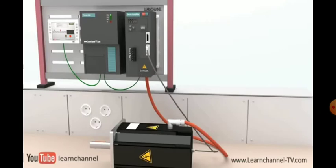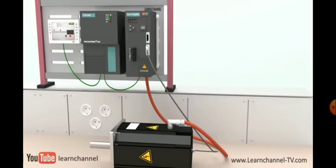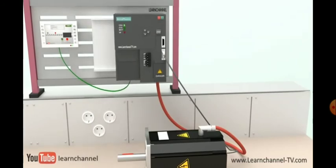The job of the servo motor controller, also named as the motion controller, is to close the loop on the system by constantly interchanging data with the servo amplifier. The motor parameters like torque, speed, or position can be adjusted immediately. Some manufacturers offer modules which combine the controller and the amplifier, so you would have fewer parts, fewer connections, and a smaller footprint.